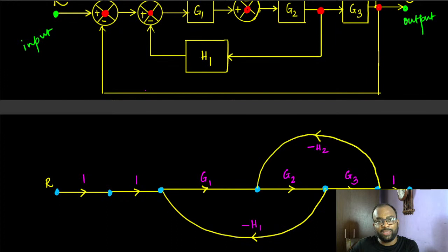And what will happen if I draw more current than that? The signal will drop, the potential, the voltage will drop. That way, the signal will become incorrect. So as long as I'm drawing less than 40 milliampere through that pin of a microcontroller, the microcontroller is happy, the signal is not dropping. It has its own internal buffer, and that buffer is capable of delivering up to 40 milliampere.